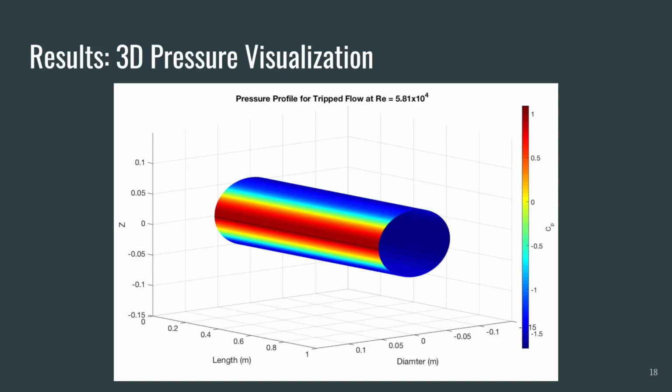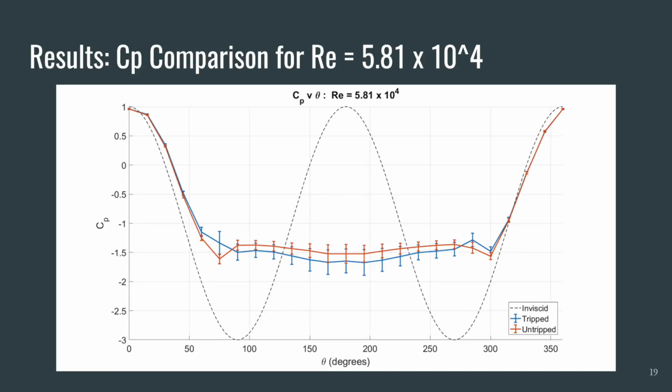It is also clear that there is symmetry over the horizontal axis going through the cylinder, but not over the vertical axis. As was mentioned previously, in an ideal case, the inviscid flow over a cylinder would not separate, and the streamlines would be symmetric across both the vertical and horizontal axes going through the cylinder, meaning the pressure distribution over the cylinder would also be symmetric about both axes.